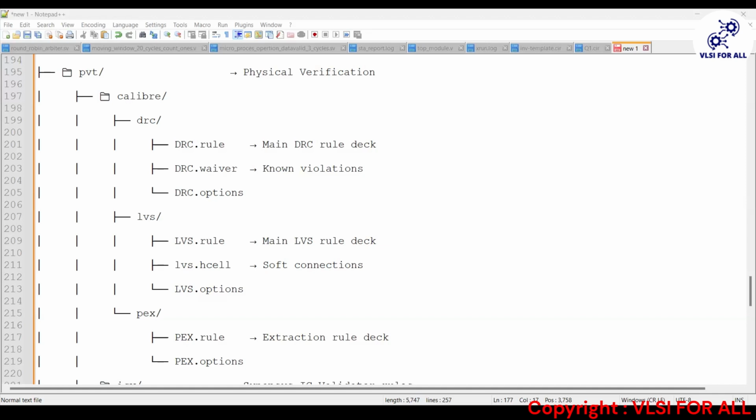After RTL, we convert that into the gate level netlist. After the gate level netlist, each gate is denoted through some NMOS, PMOS or something like that. Now these NMOS and PMOS at the layout and floor planning stage will be decoded by this type of structures. So you cannot place your contact here because it will say the minimum spacing here should be 1 nanometer or 2 nanometer. Those types of rules are there in the DRC.